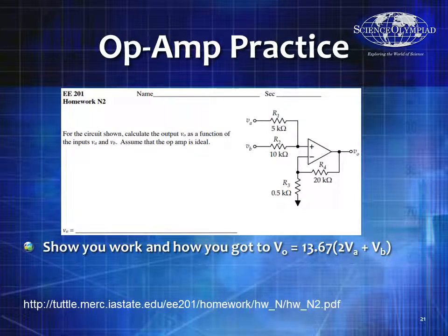Okay. Now this one, at first blush, you're like, oh my gosh, this is super complex. But in reality, this one's actually sort of simple. What's going to end up happening here is I see the feedback for R3 and R4, and it just screams non-inverting amplifier. So if I take the voltage at the positive side of the operational amplifier and call that my Vin, it is straight up a non-inverting amplifier. And so then I've just got to solve for Vn.